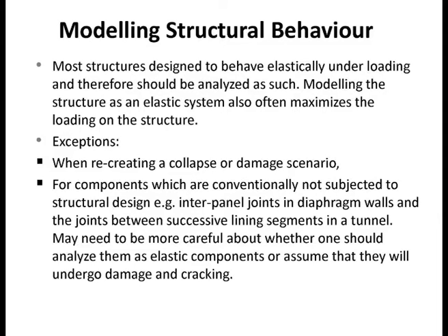And there are components because of the fact that when people design, they design in 2 dimensions. You see, if you have a deep excavation or wall, it's always done in 2 dimensions, top to bottom kind of thing. But between one diaphragm wall panel and another diaphragm wall panel, in fact, there's no steel. There's a key, concrete key, just for water tightness. But there's no steel. So there's always a question as to, is there continuity at this particular point? Where one wall keys into another, what is the effect of this key? Okay? So this is the issue that as a geotechnical engineer, if you are doing full 3-dimensional analysis, you've got no choice but to think through some of this.